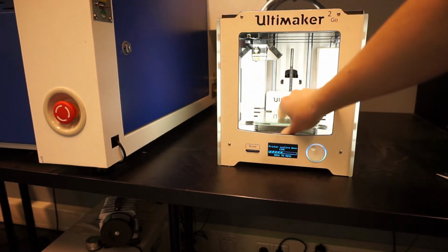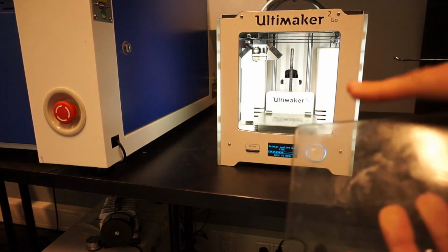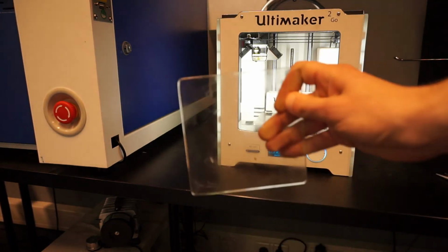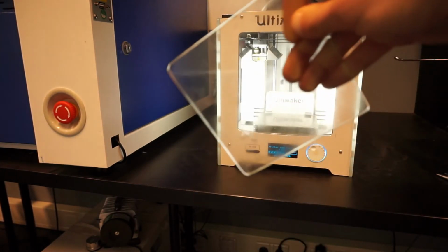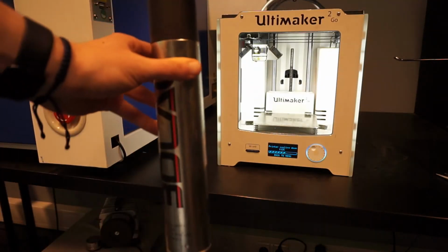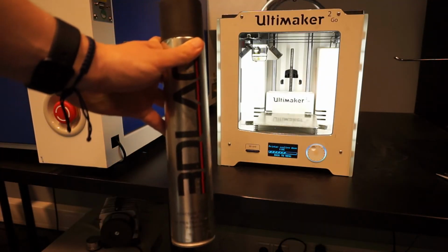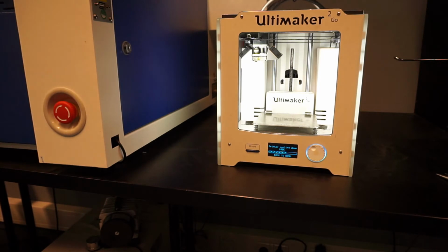To start printing, first remove the glass plate that is inside the printer. After that, spray it with the spray that is available. This is probably somewhere around the printer or in the glass doors of the closet. This spray will prevent the 3D print from sticking to the glass plate.